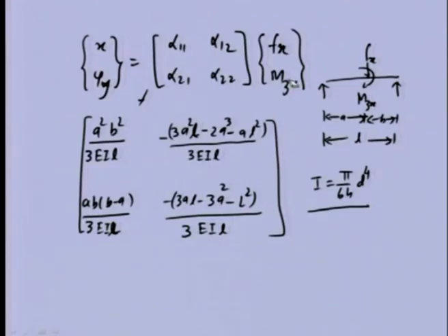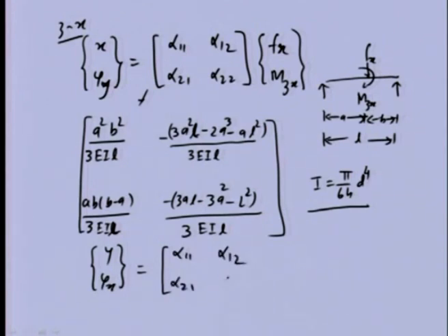So, this is the influence coefficient, and using this we have related the linear and angular displacement with the force and moment. Now, these relations will be valid for the other plane also. This was in the z x plane. A similar expression can be written in the y z plane, and because the shaft is symmetric, we will have similar influence coefficients in that plane also.